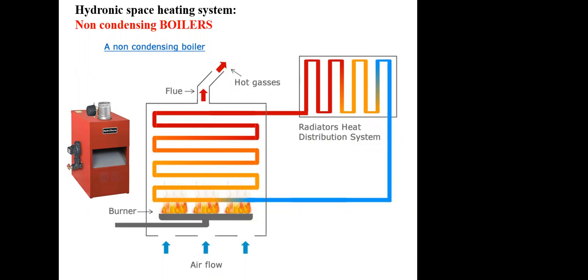Okay, so if you see your dog or your cat dying without knowing what's going on, probably you have a gas leak in your boiler. So open all the doors, all the windows, and ventilate. If you don't notice that, the gas is little by little filling the room, and when it gets to your height, you start breathing it. You don't notice because you don't feel the odor, and if you are exposed to this gas for a long time, especially during the night, you can die.